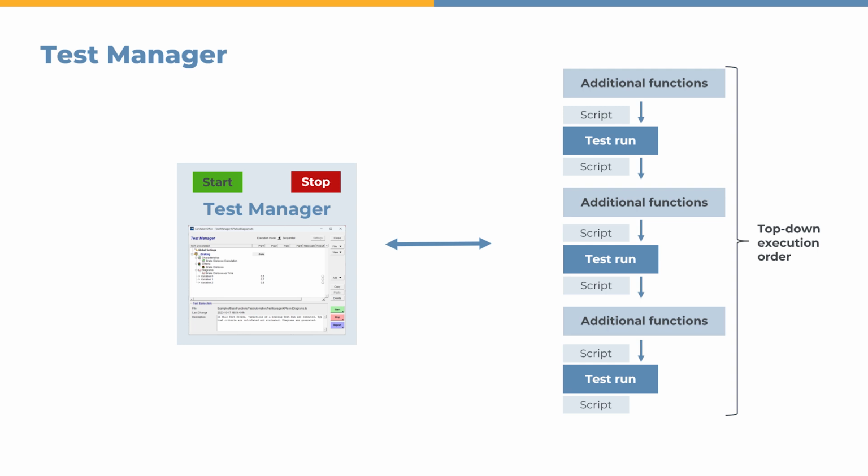It is possible to use variations to modify parameters of a test run instead of creating a test run for each and every scenario. You can add script files to define certain actions which should be executed, either at the beginning or at the end of each simulation. The definition of criteria used to judge the results can also be set up in a test manager. There's also a possibility to change the execution order internally for each simulation. It is possible to execute multiple simulations sequentially or in parallel, depending on the user's requirements.